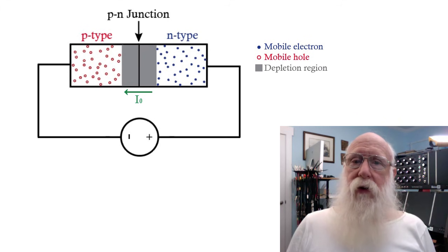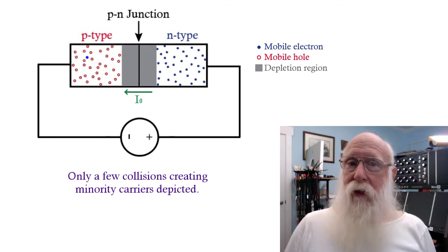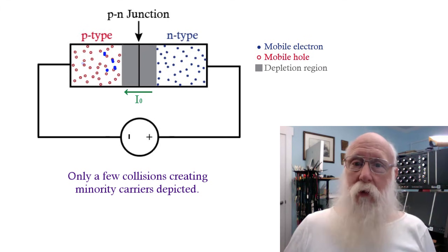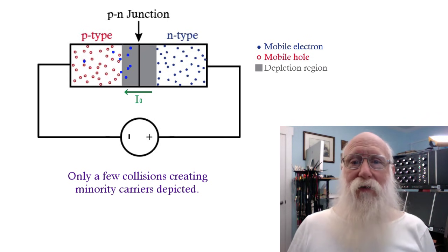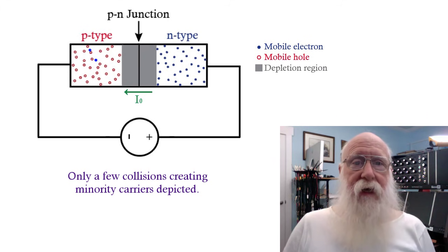In avalanche breakdown, when a thermal electron is freed up, it's then accelerated to a high enough energy by the external source that it can bang into another atom, knocking another electron free, which is then accelerated, which can then bang into another atom, knocking another electron free, and of course each time an electron is knocked free, a hole is created. This produces a cascade effect.